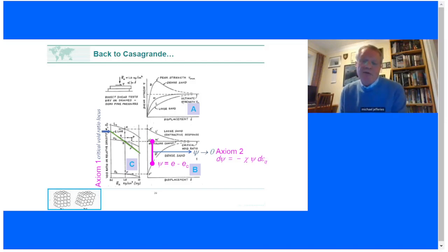And an outcome of that model, or that understanding, is an evolution of void ratio, which is on plot B. And somehow we magically wind up with the critical void ratio, and that varies with confining stress, which is plot C. So the logic from Casagrande and the logic most people have pursued is we start with some sort of constitutive model, and everything else is kind of a consequence of it.